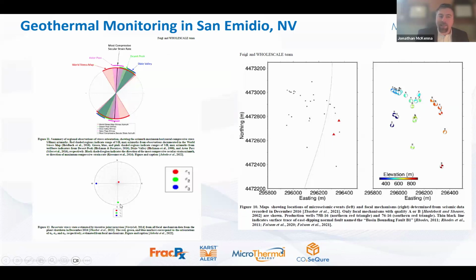This is an example that I paired with US Geothermal, where they're showing their maximum horizontal stress, SHmax, orientation. They've modeled it as being more north-south, with sigma 1 being vertical, so a normal stress regime, with SHmax being north-south, which is consistent with other measurements like the World Stress Map and other areas where they have more constrained data, where they also see SHmax being north-south.